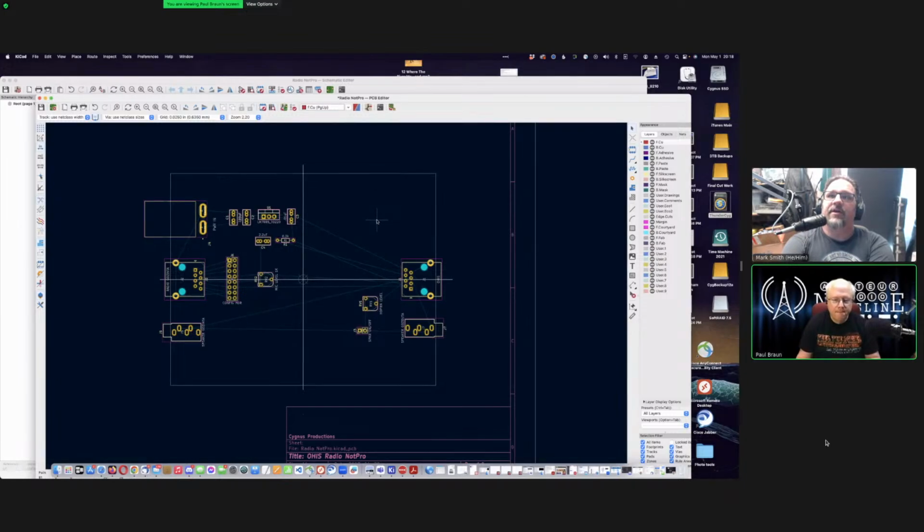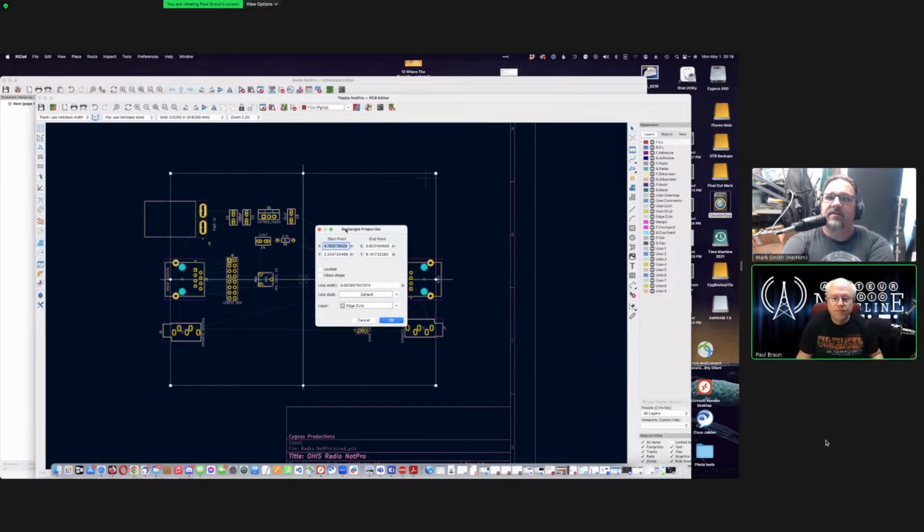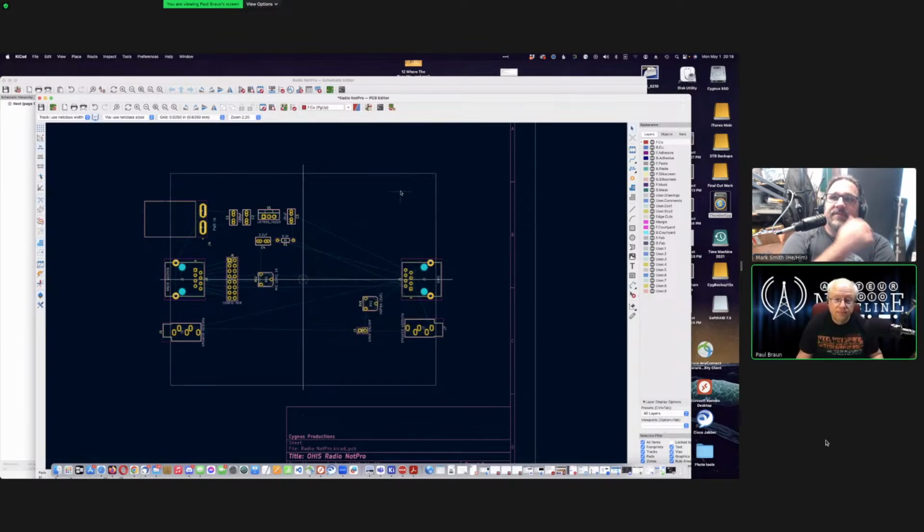Okay. Is that outer box on the edge cuts layer? What layer is that outer box on? Hit E. Yes, it is. Okay, cool, I did that right. My problem is that I use a different color scheme because I upgraded from an older version of KiCAD and it maintained the older color scheme.